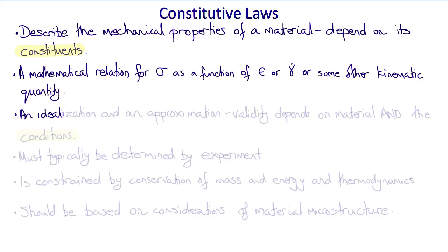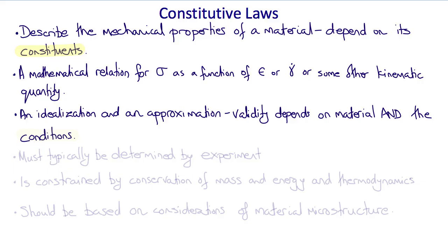The constitutive law is always an idealization and an approximation, and the validity of this approximation depends not only on the material to which you're applying it, but also the conditions under which the material is being loaded. For example, under working loads, a material might be well approximated by one constitutive law, but under loads that would cause it to fail, a different law would be needed.